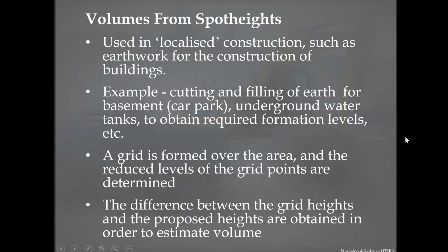Now, the second approach of calculating volume is using spot heights. As I said earlier, when the construction is localized at one particular spot, like a shopping center, a stadium, a housing estate, or something similar, spot height will be the best approach to use.